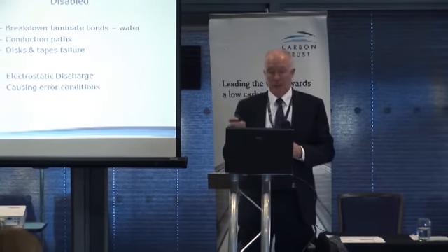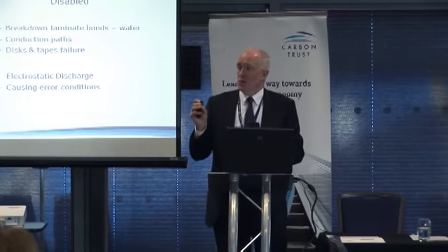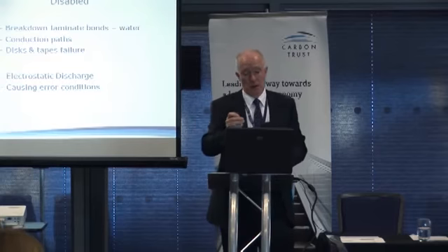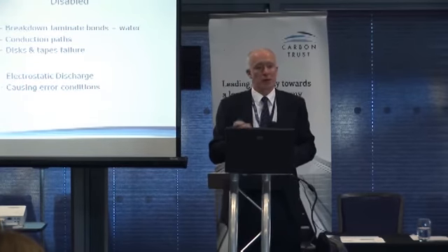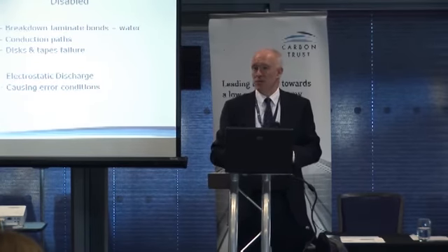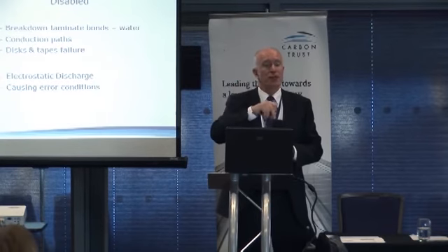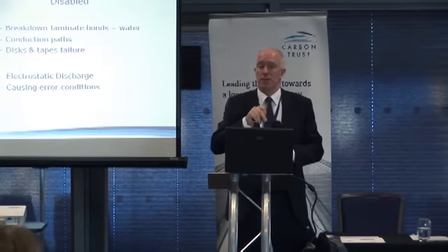So as a general principle, in terms of practice, talk to your IT managers about changing the air conditioning settings, if you've got air conditioning, to at least 24, above 24 definitely, and pushing up to 26 degrees centigrade is where best practice is, and there shouldn't be any problems with kit in doing that. Again, let them just slowly pull it up. But that is the air on temperature to the computer equipment.